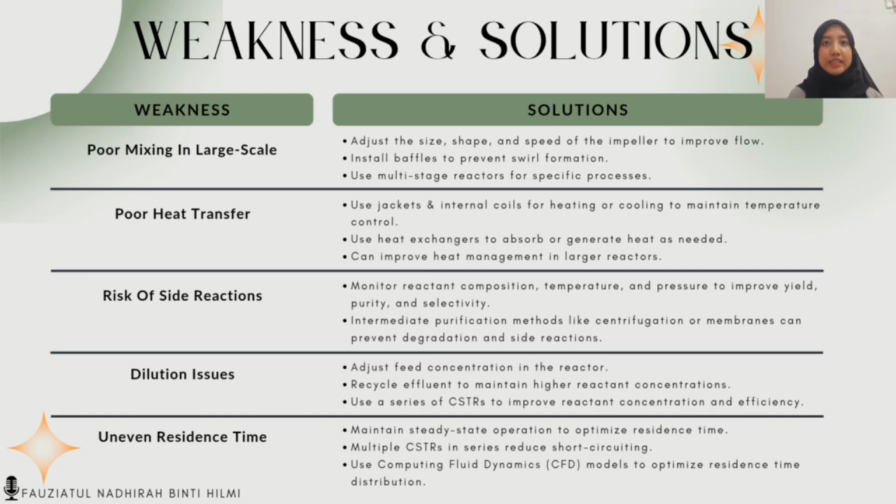The last one is uneven residence time, where it needs to maintain steady state operation to optimize residence time. Multiple CSTRs in series can reduce short-circuiting. Other than that, the use of computational fluid dynamics models also can optimize residence time distribution.